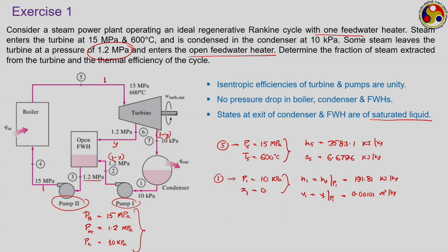Then in the pump it is raised to point number 2, and therefore, for point number 2 we know that the pressure is 1.2 megapascal, and this being isentropic, s2 is equal to s1. But for pumps, as they deal with liquids, we do not have to think about this isentropic relation s2 equal to s1; rather, we can directly calculate the pump work.